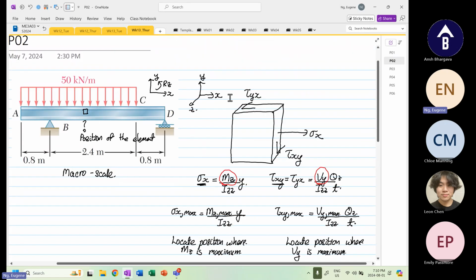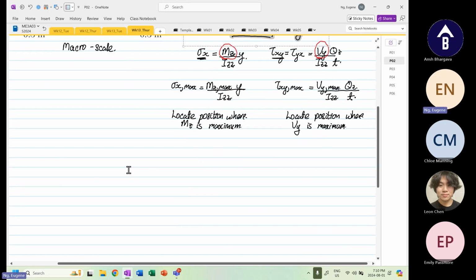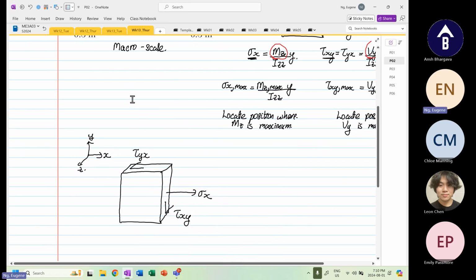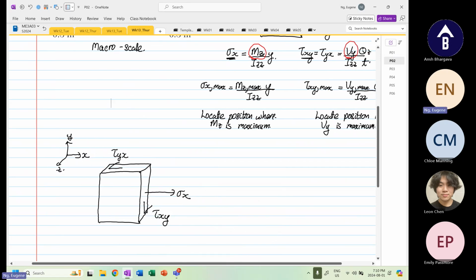going to use what? And from here, right? From here, we are going to construct, right? So we're going to construct 3D Mohr circle, right? So from here, we are going to construct 3D Mohr circle. Okay, normal stress, shearing stress. Okay, so we know that this is our stress X line. This you know is our stress Y and stress Z line, right?